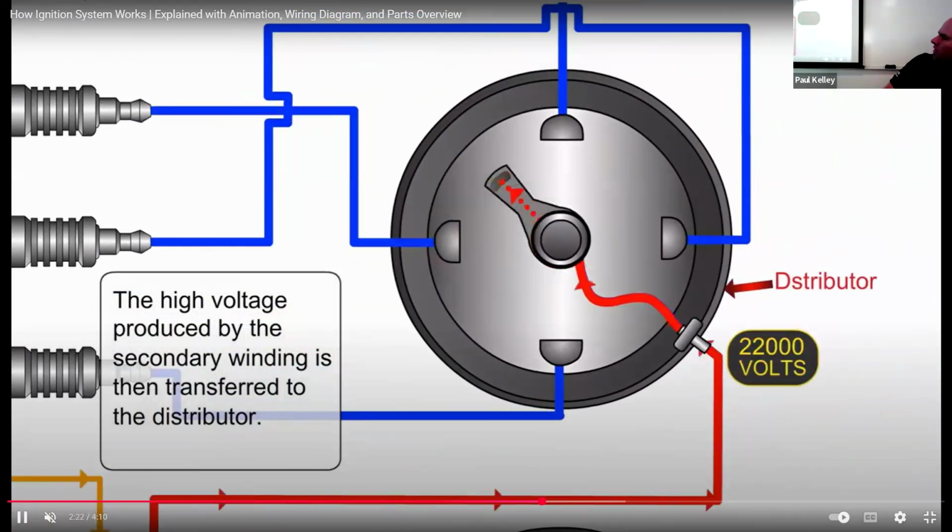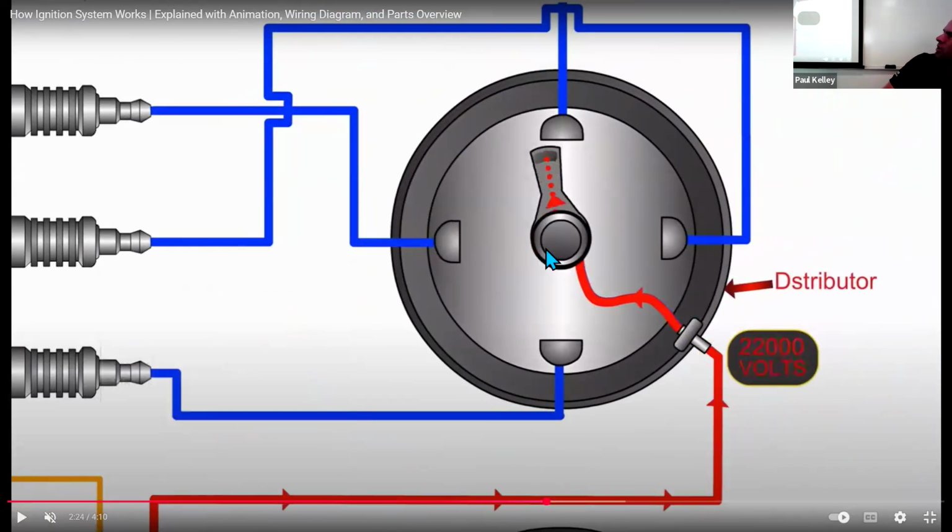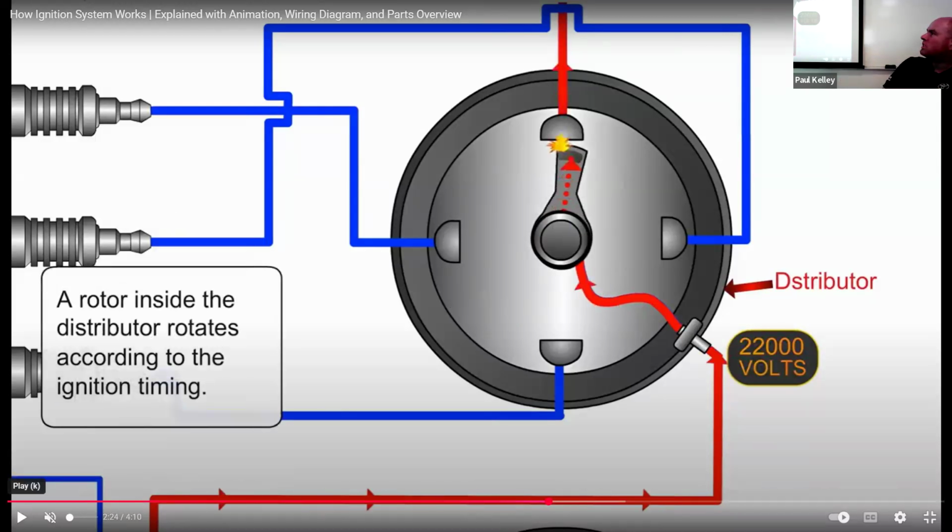And the distributor, if you look, all the distributors have a center connection on the top in the middle. That center connection comes from the coil like this. That's where it's going. It looks like it's going in the middle, but it really goes over the top, kind of. And then right here, you've got 20,000 volts ready to go, but it's got no good path to ground, right? When it gets right here, notice it's not touching. But when it gets close, that gap's small enough, 22,000 volts can jump that gap. You want to see? Boom, do you see that?